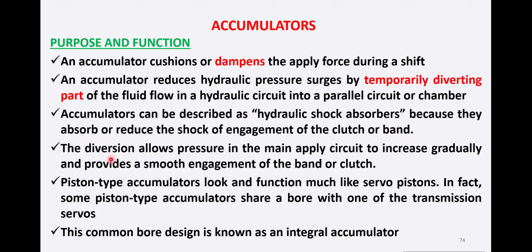The diversion allows pressure in the main apply circuit to increase gradually and provide a smooth engagement of the band or clutches.